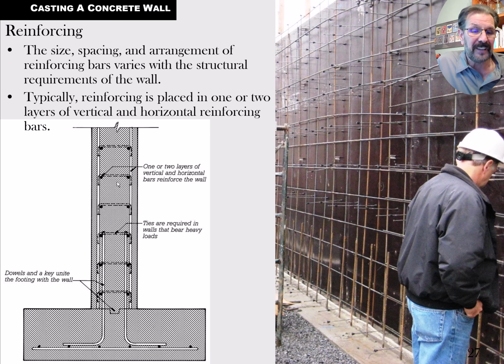But it's not necessary for it to be a keyway. It could be just chopped up rough concrete. And so that's another way to do it. Depending on the engineer and what their real experience is with concrete, the traditional textbooks show a keyway like this, and so a lot of engineers go and try to put that in there, and they can, but it's not always necessary.